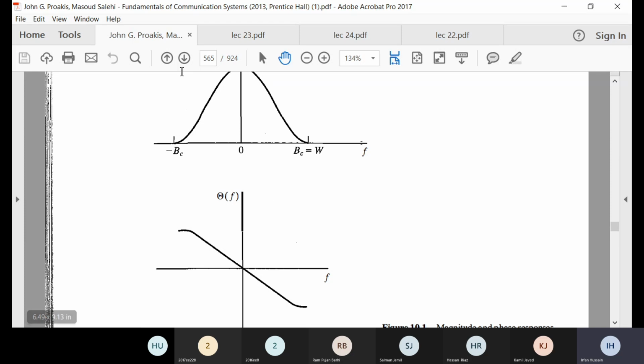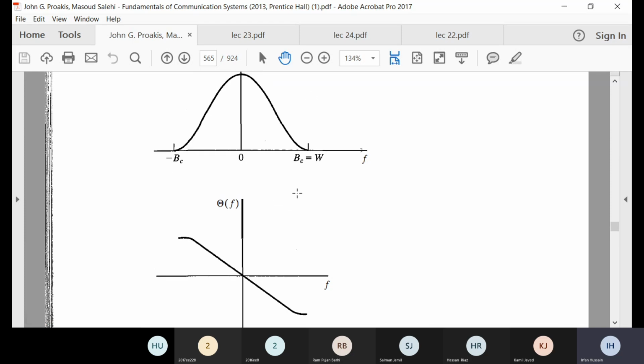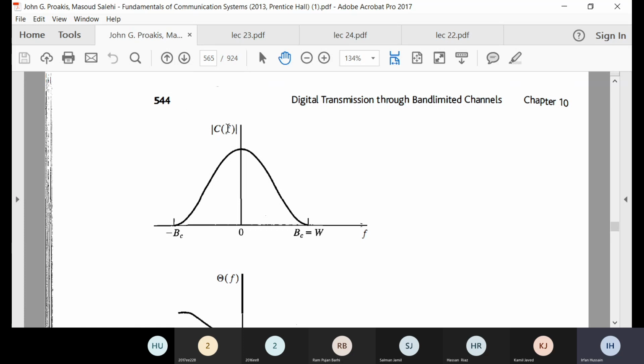So if this channel is conjugate symmetric, this means that this channel will have real coefficients. If you have real coefficients, then no problem. Your C is real, and the convolution with G is also a real signal. The H will also be real.